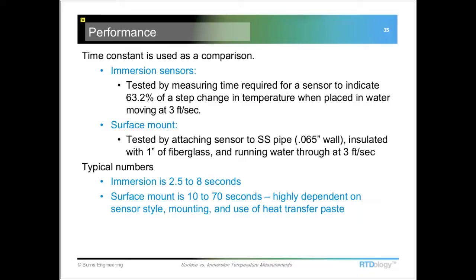Yeah, we do see silicone oils used a fair amount if the application is in a vertical orientation, so it doesn't flow out. But when it comes to the pharmaceutical arena, most folks aren't real comfortable with putting one additional component in there. So we're typically looking at trying to find a different way to get good contact, and they're typically within a thermal well. So then it's just matching up the size of the sensor with the bore of the thermal well to make sure you get a good fit, and making sure that sensor sits down at the bottom of the thermal well. So that's some of the things that we're dealing with there.